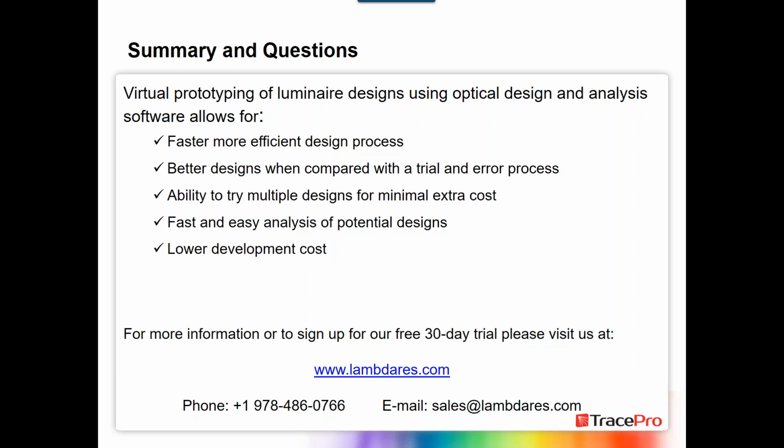Got another question for you. How do we specify the target shape and distance from the reflector in the optimization? Well, it actually uses the model in TracePro. So in TracePro, you would have the reflector or the lens set up, and then you'd have a target placed where you're interested in the results. And you name one of the surfaces of that target, for example, detector or wall. And in the optimizer, you tell it, I want to see the irradiance or the illuminance on that particular surface. So you set it up. The optimizer doesn't know what the distance is. That's set up and defined in the TracePro model.